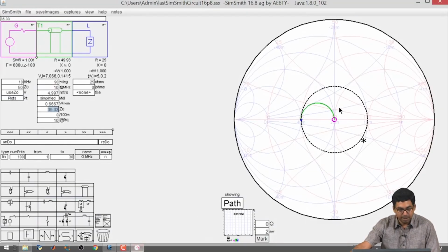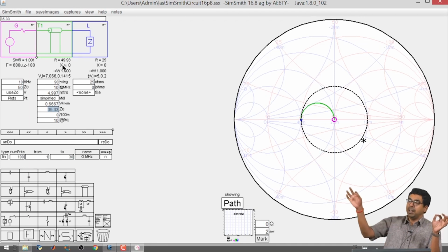I will go back to this diagram. You will have a 90-degree phase producing transmission line of a characteristic impedance, which is the geometric mean of this input impedance here and your load impedance, and then that is going to produce impedance matching. Remember that we have taken lossless conditions. So, we are starting with the horizontal axis and ending at the horizontal axis also.